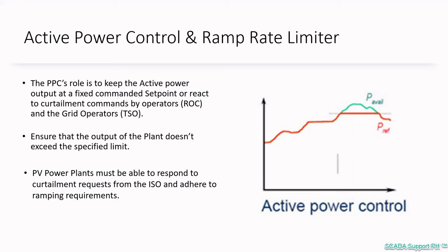The solar PV power plant must begin the alteration of the absolute production constraint set point within 2 seconds and must complete it within 30 seconds of receiving the modification order. This is especially important for plants in the US, like those in California, that are participating in the real-time energy market.